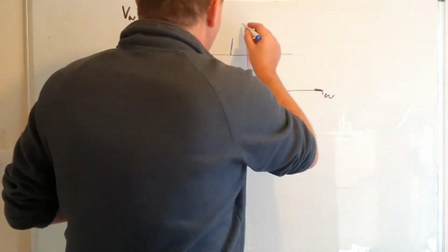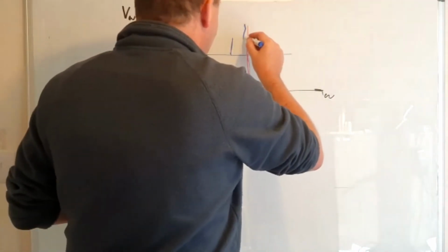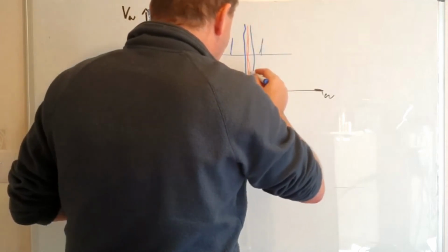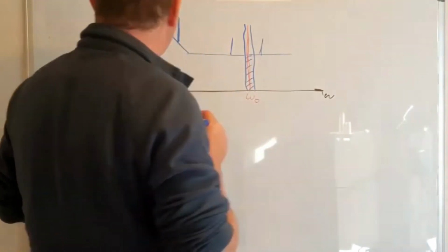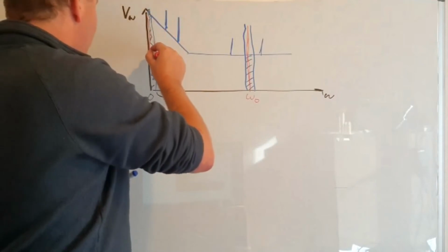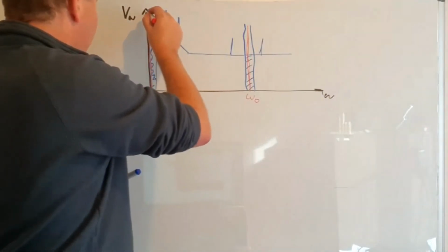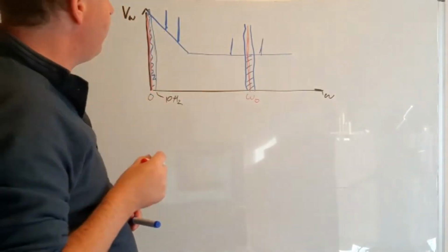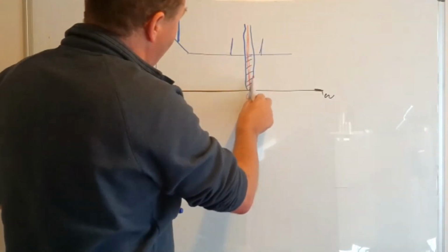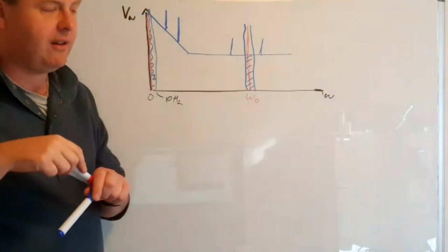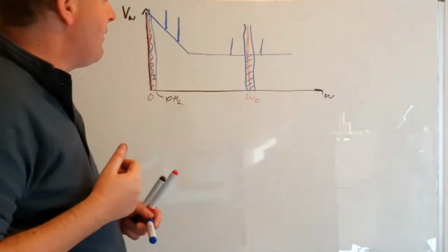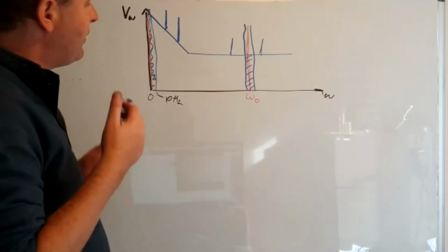So what we're going to do is the same 10 Hertz bandwidth measurement. And now what we're seeing is we'd be measuring that much noise. So in this region down here, when we're actually trying to measure the DC thing, basically our entire signal was covered in noise. Whereas now, if you look at this case here, we're seeing our signal clear, and we've got this much less noise in the background. And so we're actually getting a better measurement by finding a frequency range in which the measurement is going to work better. So this is what's going on with phase sensitive detection.